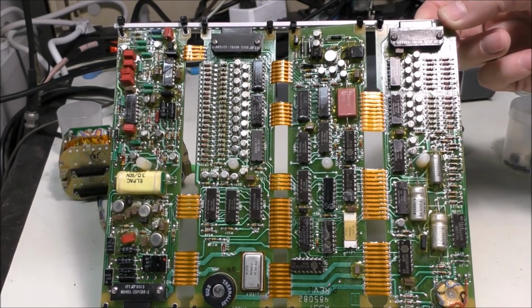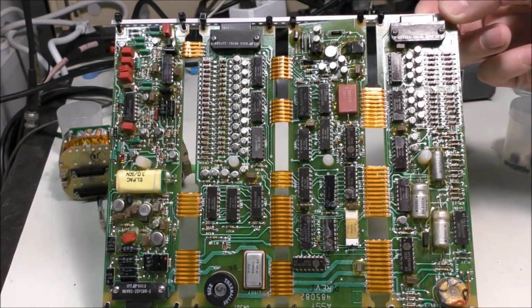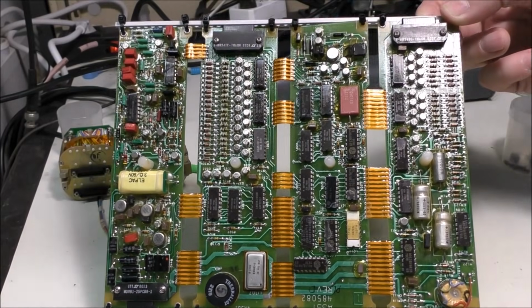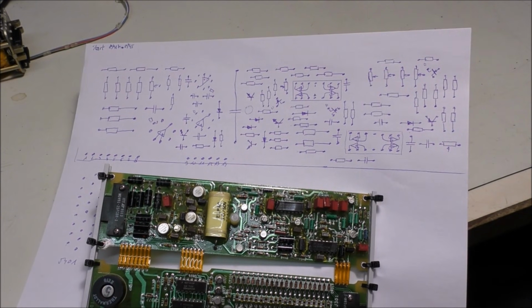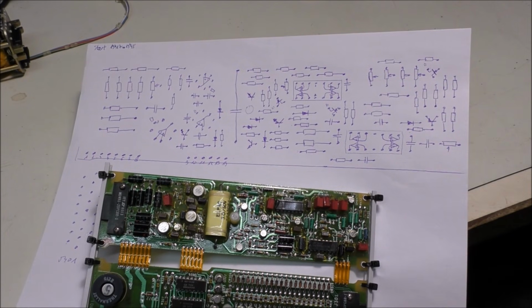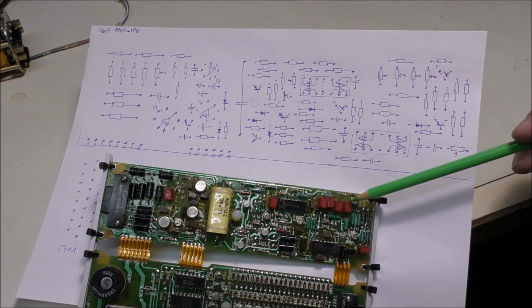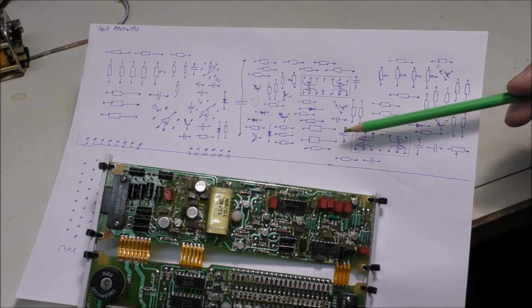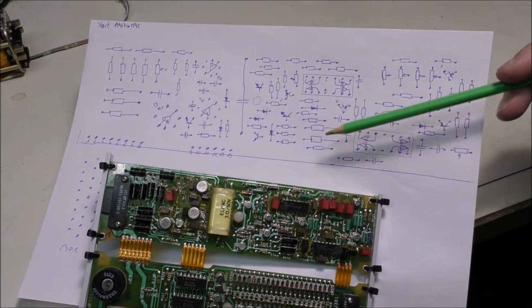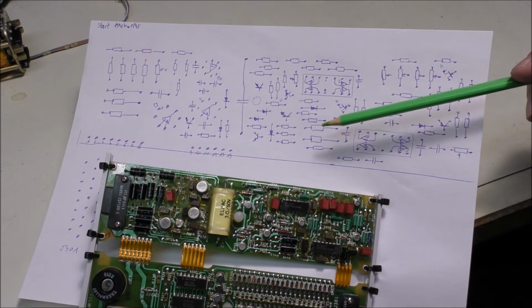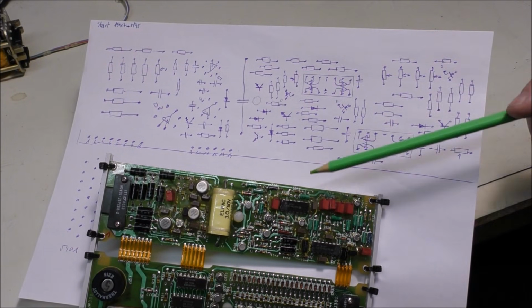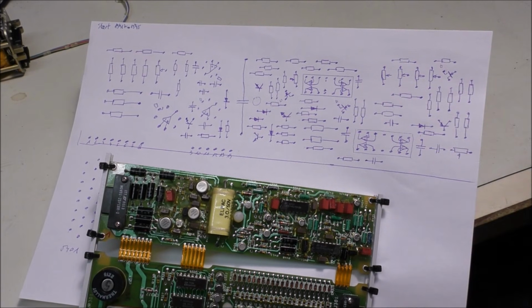For the reverse engineering, I have attached these 4 boards in order to have something rigid. This is the first step of the reverse engineering. I have started with this board here. Each part is placed on this drawing using an appropriate symbol. Okay, for example, the N-channel JFET, a quad op-amp, transistors, diode, and so on.